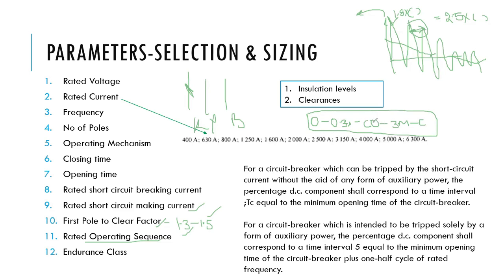But if you open, then two times opening is happening. So the SF6 gas which is present in that, when it's opening, two arcs are forming. So the SF6 gas which is present there gets ionized. So it requires some time to deionize, or to again regain its dielectric strength. So we require some time, that is nearly 3 minutes. Then you can again close the breaker. So this is the duty cycle of the breaker.